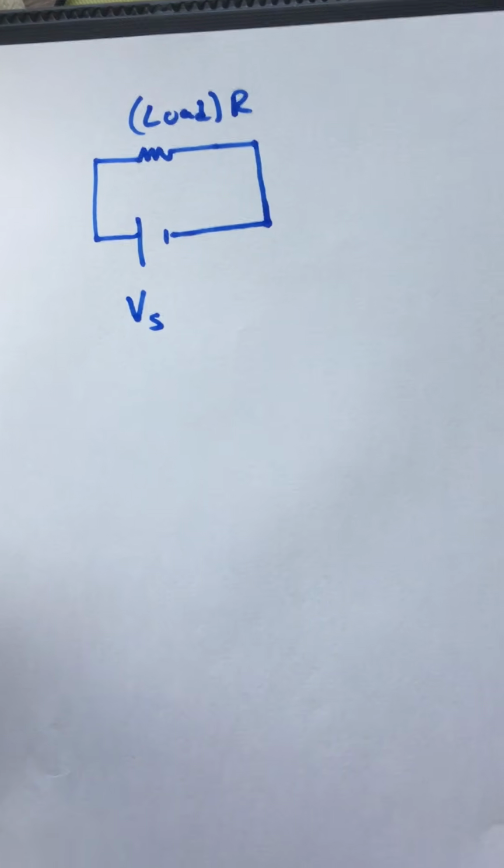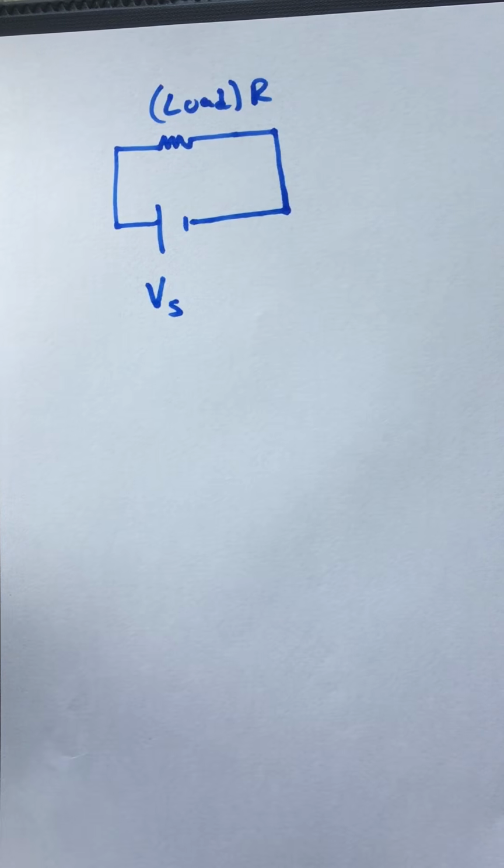So in the last video, we looked at the difference between generators and motors. Specifically, we looked at generators and how the motion of a coil in a background magnetic field produces an EMF in the coil. Now, what we didn't really specify there, because we're going to talk about it here, is that the EMF that's induced produces a current, which produces a magnetic field which interacts with the background magnetic field to oppose the motion.